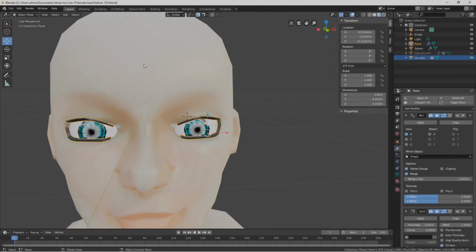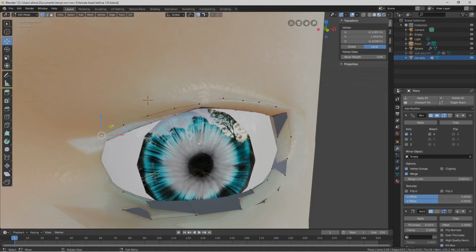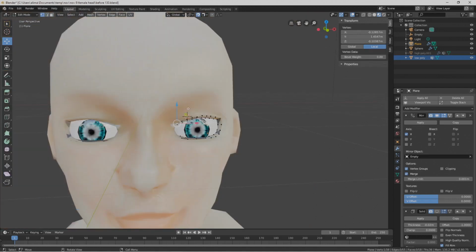Okay, with this selected, I'm going to turn the solidify modifier back on. I'm going to go to the upper left, go to edit mode. The reason why we're coming in here is I'm going to go to vertex select. I'm going to left click on a vertex right here. I roll the mouse wheel to zoom back. I'm going to hold shift and then press D to duplicate this vertex, to move this vertex up here like that.